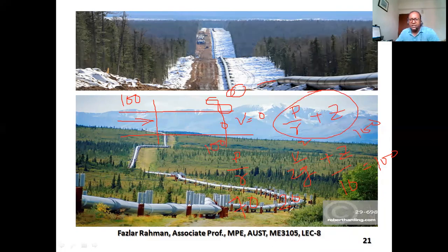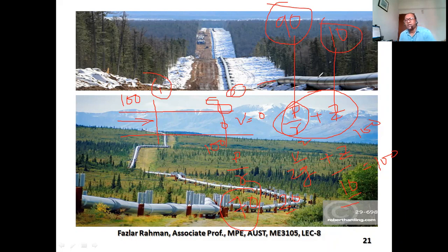It will be the same or it will increase. You see, Z is 10. So this is 10. Now to make 100, how much does this value have to be? This value has to be 90. So you see, pressure energy at point 1 was 70. At point 2, it becomes 90, because total energy always has to be 100.